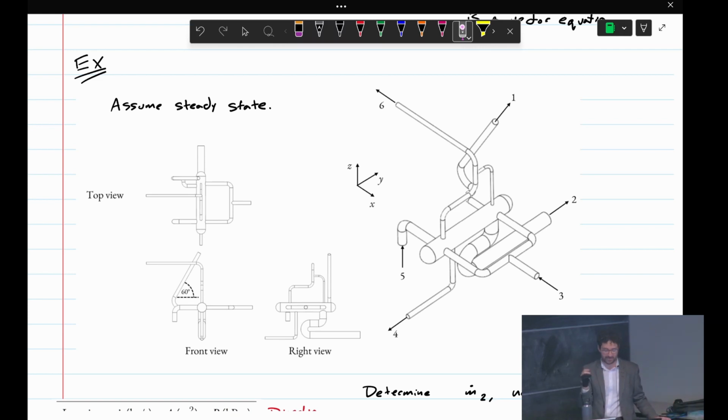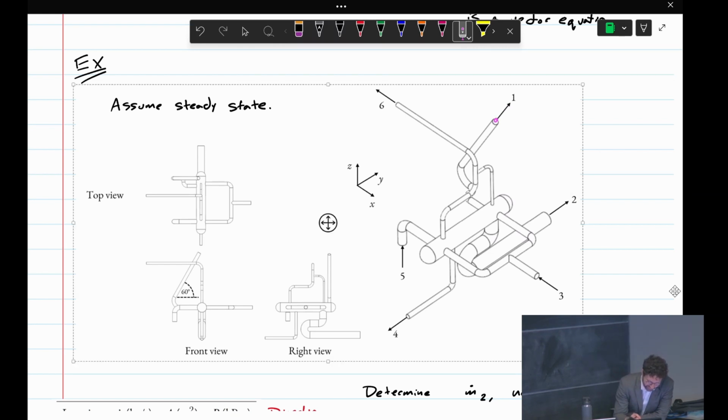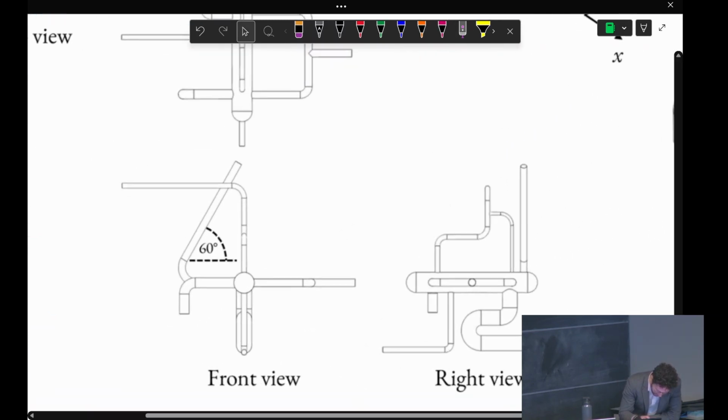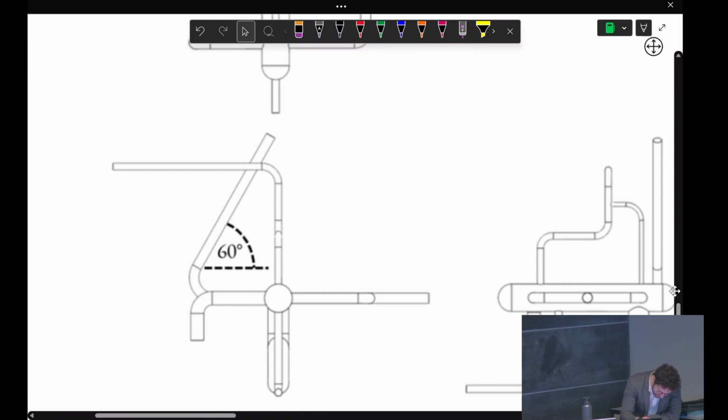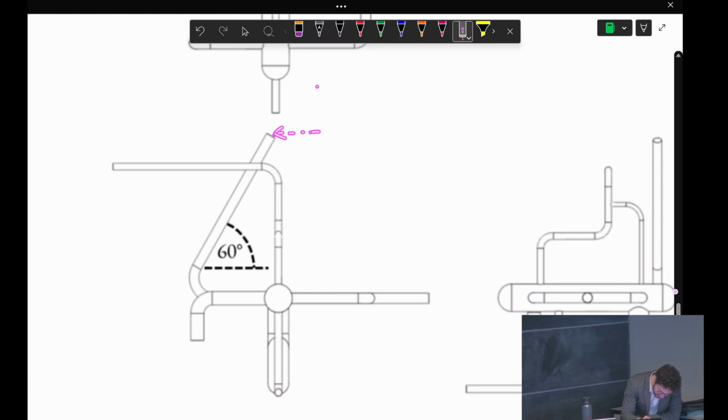That's just for an outlet though, right? For an inlet, it would be the same direction as the flow, like for here, right? So the pressure force always points into the CV. So when they're on the right-hand side, forget about your inlets and outlets and things like that. Just think about the pressure force points into the CV. So always pressure force into the CV, regardless if it's an inlet or an outlet. So pressure force into the CV, if I go to our front view, looks like this. So it's going to have that positive x direction component.